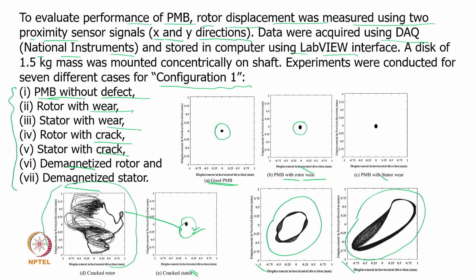So, out of the 7 factors, the cracked rotor has a very high importance and should be addressed immediately. Then demagnetization is next. Why does demagnetization happen? What we selected was a stator magnetization of 1.4 Tesla and a rotor of 1.04 Tesla. The magnetization strength of both rotor and stator must be the same.